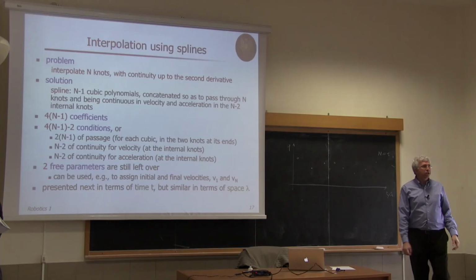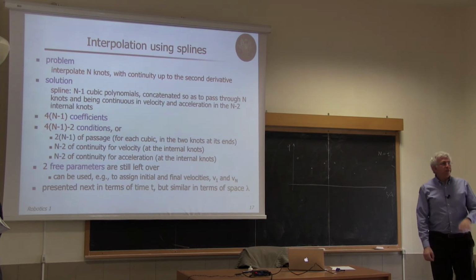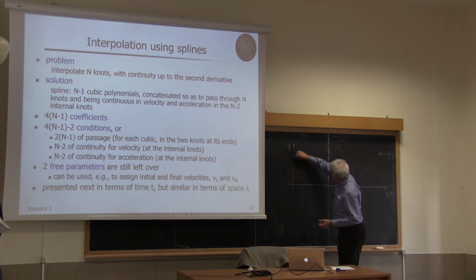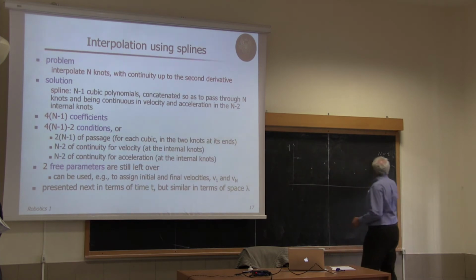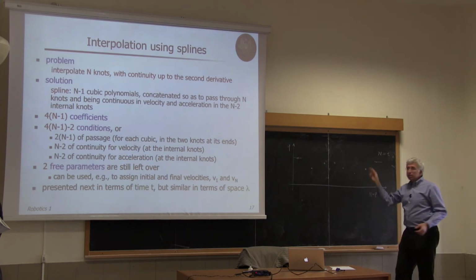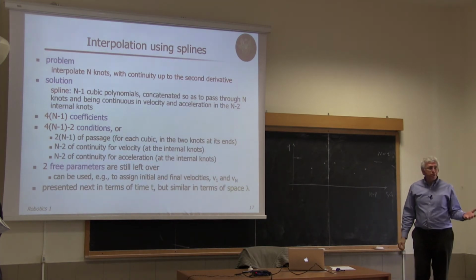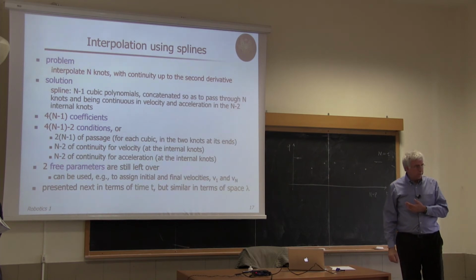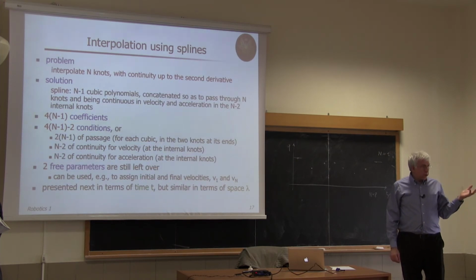It's already a good number. If I want to impose, let's say, start zero velocity and final zero velocity, so n equal to 8, plus the 2 initial conditions, 10 conditions, I need a 9th order polynomial. Okay? So a 9th order polynomial, its first derivative will be an 8th order polynomial.